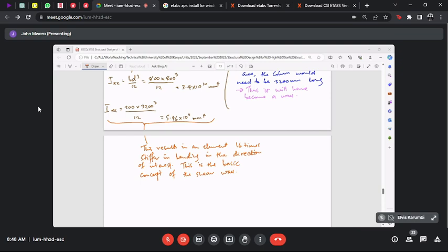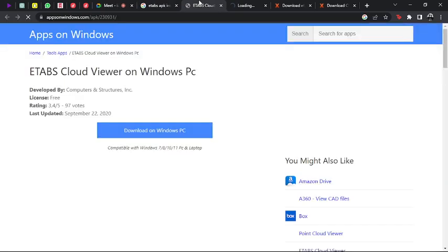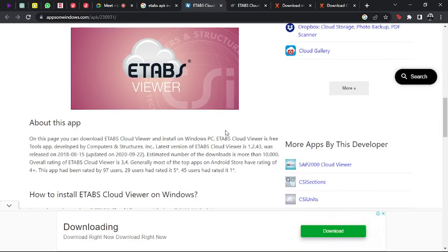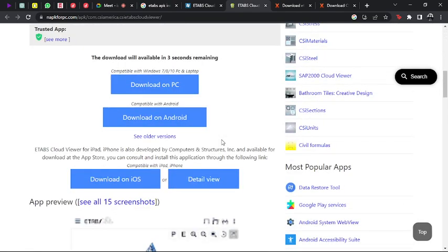For wind, you want to make the surface complex so that it confuses the wind vortexes. This is what we said when we were discussing wind. For earthquake, in the plan area, the simpler it is, the better it is in terms of how the building will respond to earthquakes. I will remind you that I've said this is a pretty complex question that maybe I might not be able to give you a yes or no answer, or if this happens, then this will happen. But these are the general thoughts that govern what you're asking. I hope that helps to start you off.